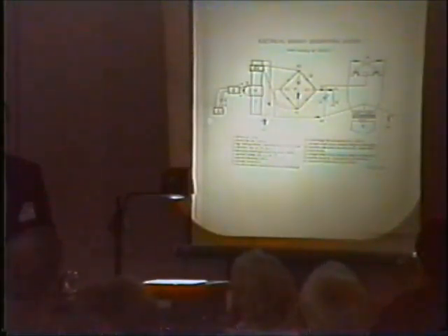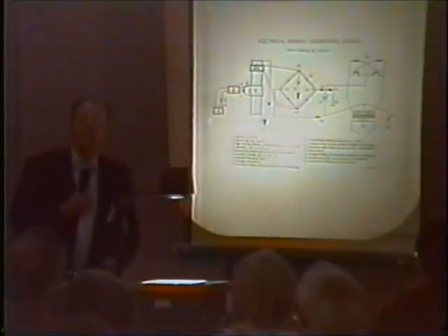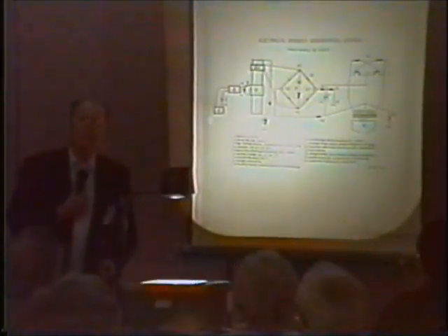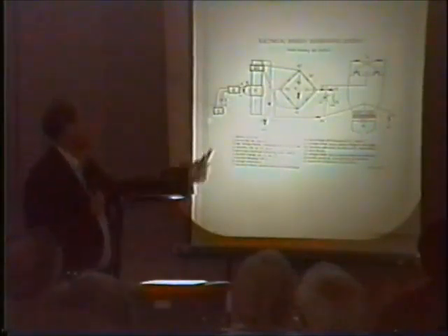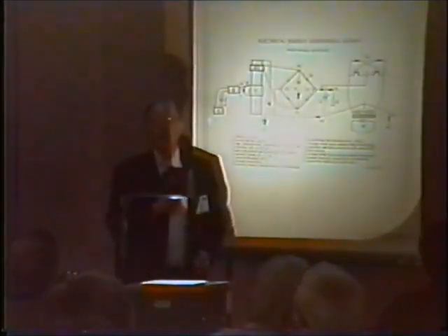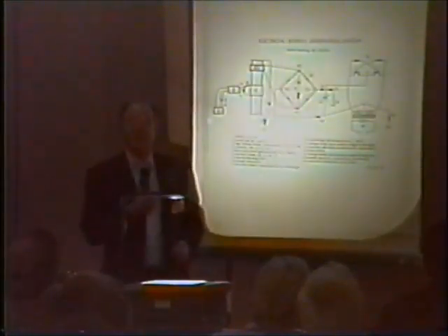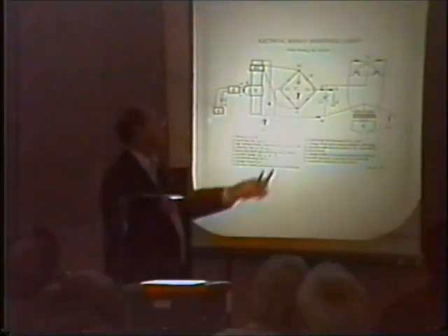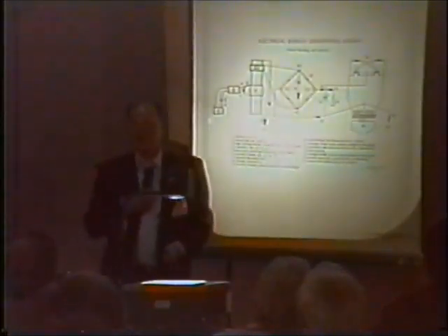Is there some place to start with the value of those resistors, like number 11s? On the dividers, these voltage dividers here, what those are doing is correcting the voltage so that when you get downstream, you've got what you need. You notice there's one on the plus side and one on the minus side. And there's also a capacitor in here to take the ripple out, because when you come through that diode bridge, you've got rippling DC.